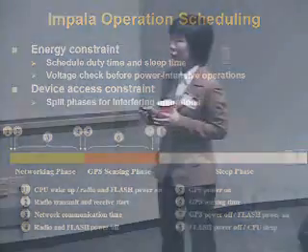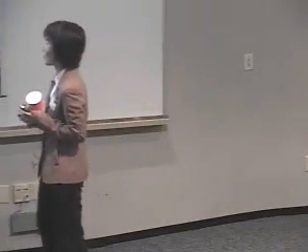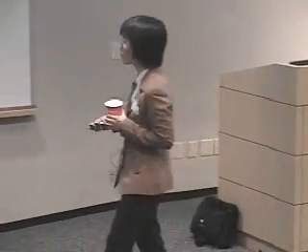For reliable operation scheduling, we first need to consider the energy constraints. Because we know the desirable sensing and communication frequency in our system, that also determines the desirable volume of the overall system activities. So it's unreasonable to make the system fully on all the time. We schedule the duty time and the sleep time. In the sleep time, we turn off all the peripheral devices and put the CPU in the low power mode. Basically, let it run at the 32 kilohertz clock.